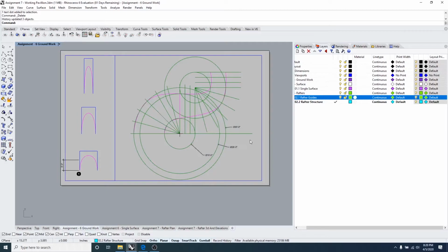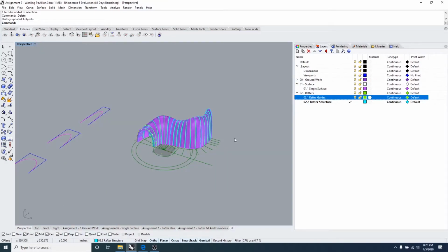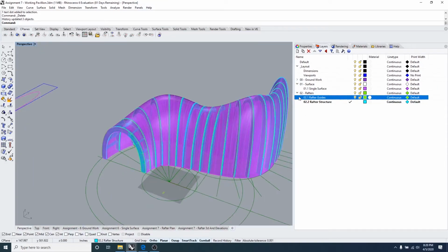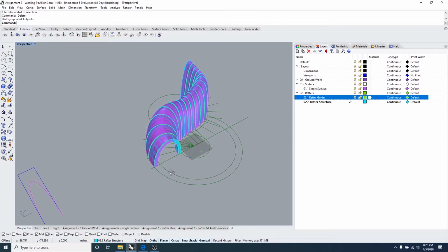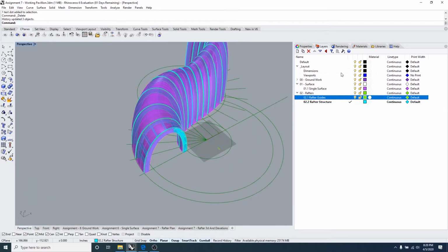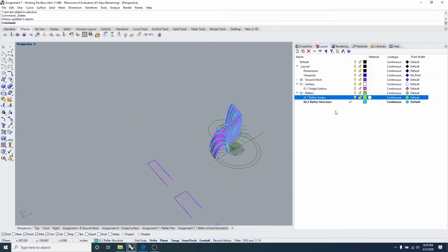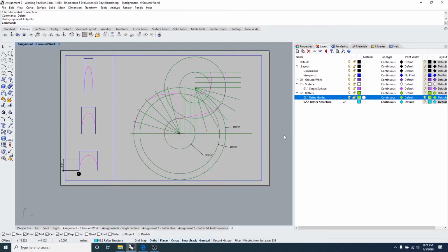I'm going to get out of my viewport and go into my perspective. And you can see that everything is still on in here. That's the way that we want these assignments to be portrayed. We want in our current model view in here, we want all these layers on, but when we go into our assignments, we want to control the layers of our active viewports with these visibility light bulbs that we have in here.